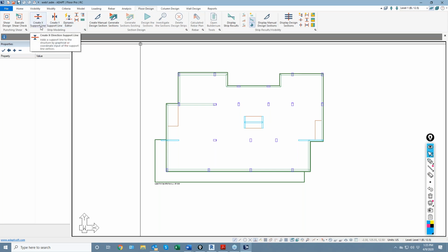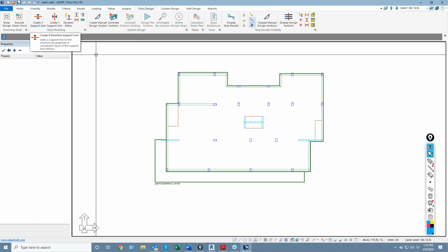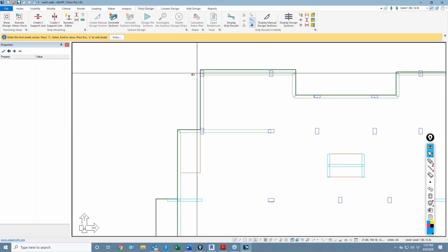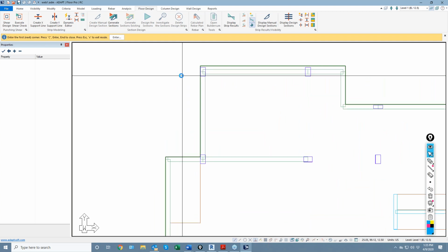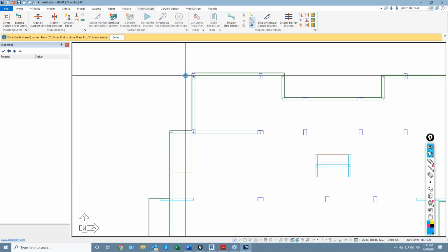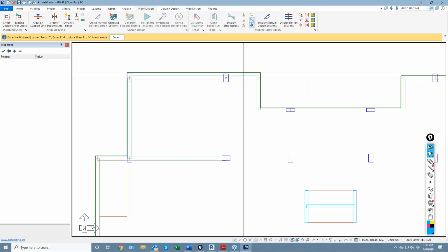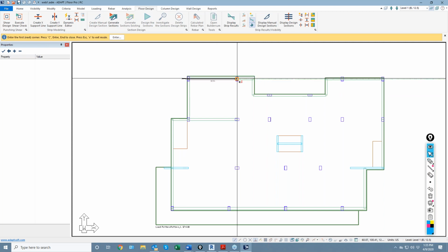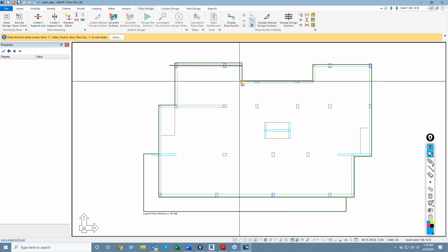the design strips. I could go in and I could just basically manually create the design strips. So for example, if I want to create strips in the X direction, I'll do the column strips or the beam strips first. And you'll notice a lot of times I'll actually snap outside the slab boundary, because I simply don't like to zoom in and zoom back out when I'm working with strips. So I'll go ahead and I'll just snap out here, and I'm going to snap at the endpoints of beams, and I'll close that off at the slab edge.